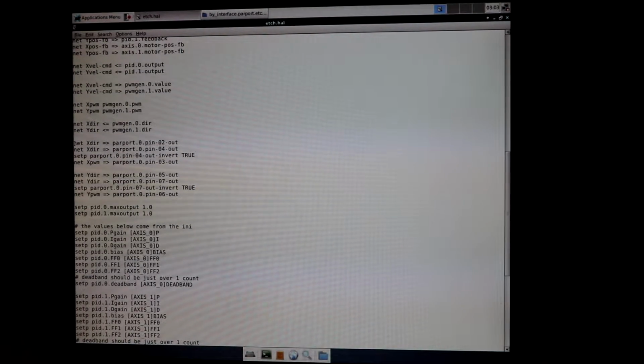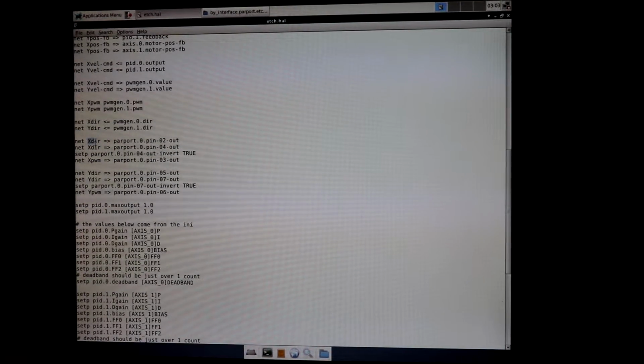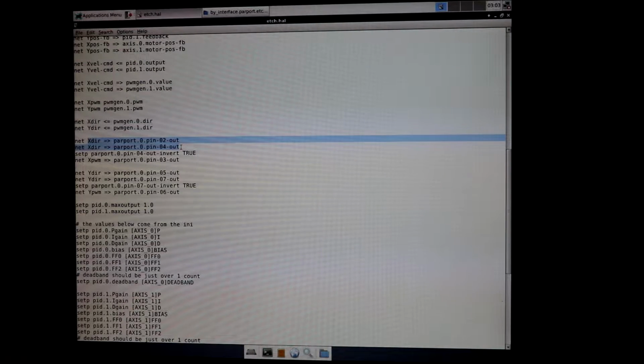So one thing you should notice out of all of this is that when it comes to driving a DC motor in this configuration, they use 2 pins, right? That's because the motor driver, the full bridge that they're using, works on a truth table, or works on 2 inputs, right? And for 2 different inputs, you get a certain output. That output being how the electricity flows to make the motor turn in a certain direction.